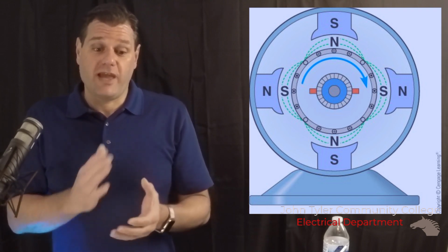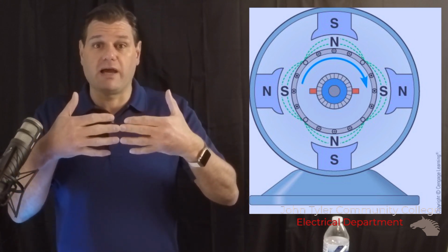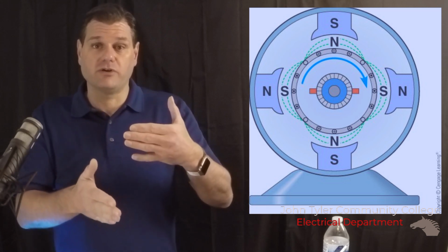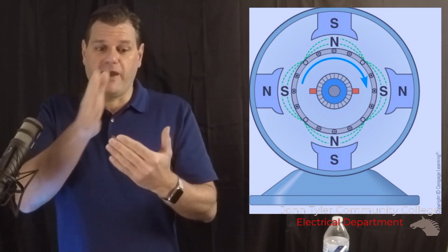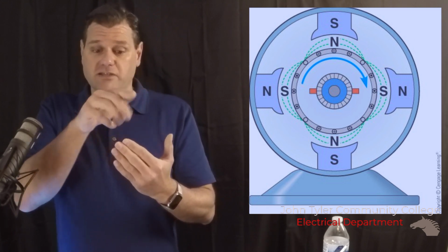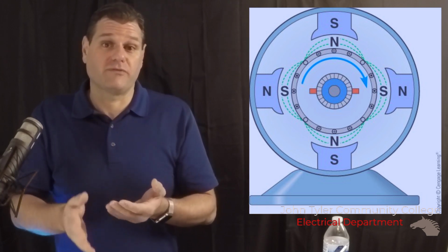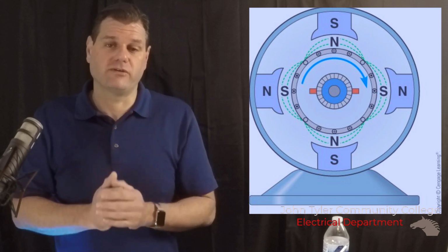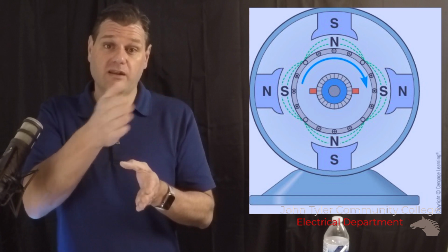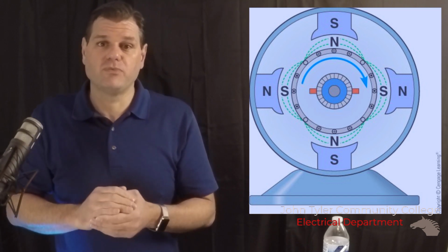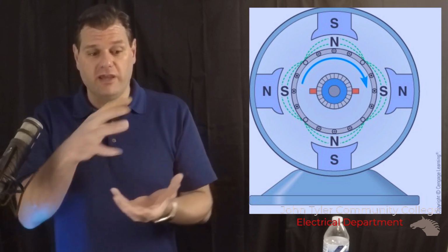So what happens is we kind of lose our position. Remember earlier we had these perfect straight lines. These straight lines were allowed to cut the flux at 90 degrees. But if they're skewed because it's rotating, now our brushes are not set to cut through the electromagnets at the right angle, allowing it to not be 100% efficient. So we've got to change that. That's called setting the neutral plane. Setting the neutral plane is actually moving the brushes mechanically to adjust for that movement. Another option is to have another set of compensating coils, which would turn on and pull it back in.